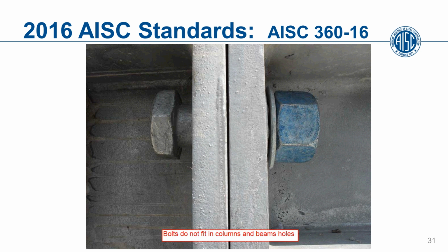So upon investigation, we discovered that there was research that was done as long ago as the 1950s saying that a 1/8 inch oversized hole does not adversely affect the strength of the bolt in the least bit. Now, granted, we are conservative when we make these changes, and it took us since the 1950s, but we're making the change now that for 1 inch and larger bolts, you can be at 1/8 inch oversize. Now keep in mind, it's permitted to be a 1/8 inch oversize hole. You still can use a 1/16 inch oversize hole if you would like. There is no effect on strength either way.